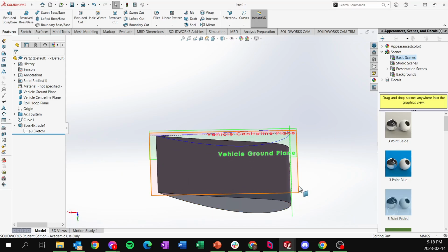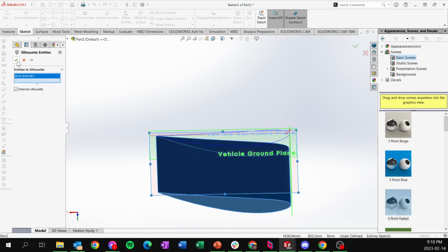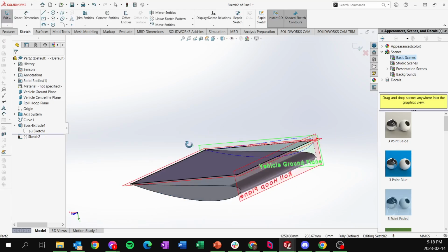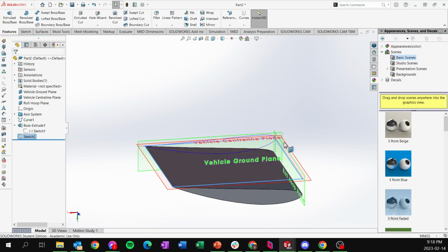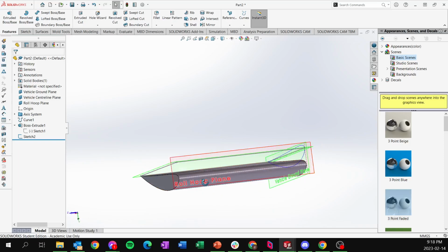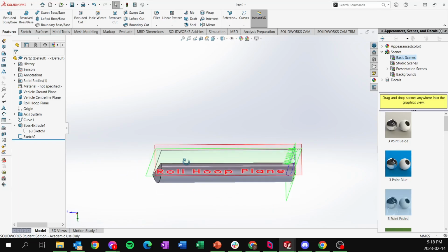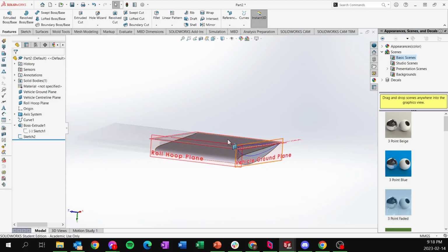Here's another little fun thing. If you ever want to get the planform area of something or the frontal area of something in SolidWorks, you can always do something called the silhouette. And that's basically going to get you this silhouette of it. And then you can measure that, or to get your top area, you can do the same thing for your frontal area as well. But yeah, all right, so we have our wing. That's one way of doing it. Let me go ahead and hide this.